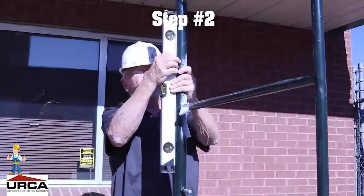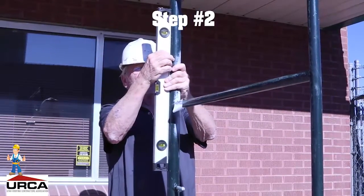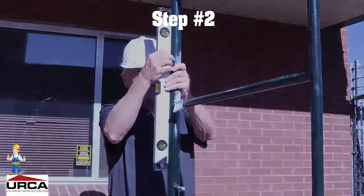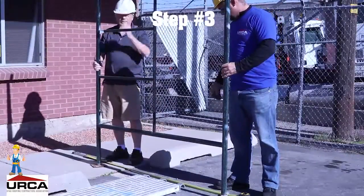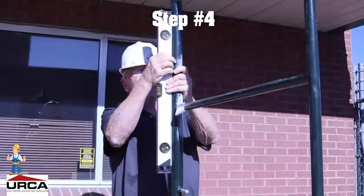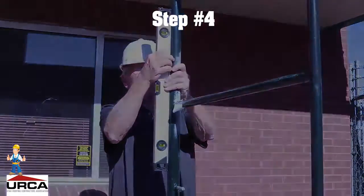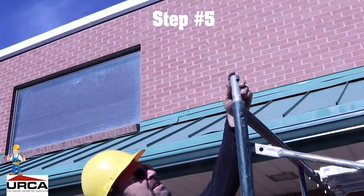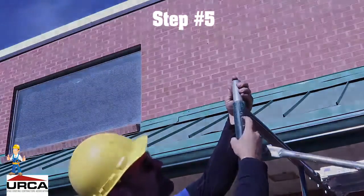Step number 2. Plumb and brace poles, legs, posts, frames, and uprights to prevent swaying and displacement. Step number 3. Position the first level of bracing as close to the base as possible. Step number 4. Plumb and level the scaffold as it is being erected. Step number 5. Fasten all couplers and/or connections securely before assembling the next level.